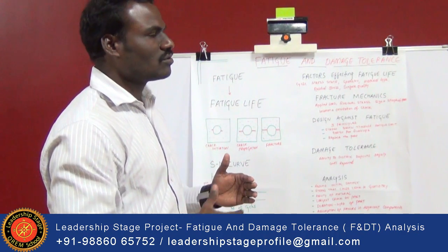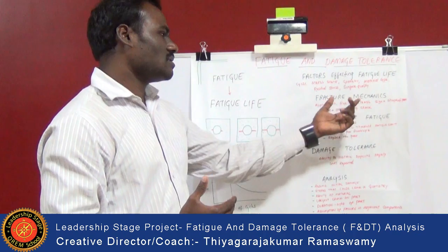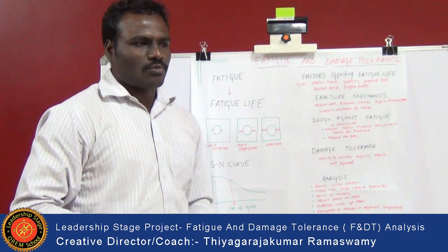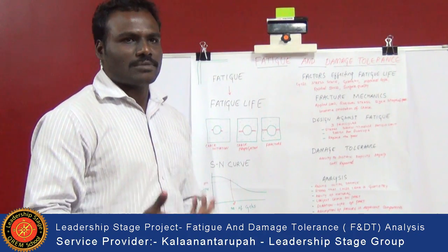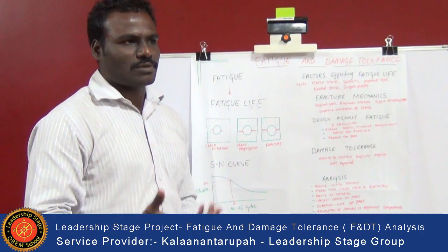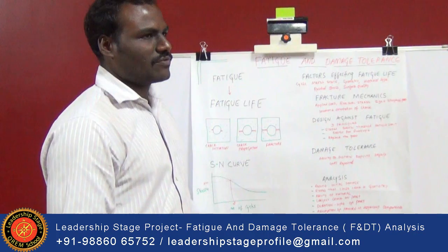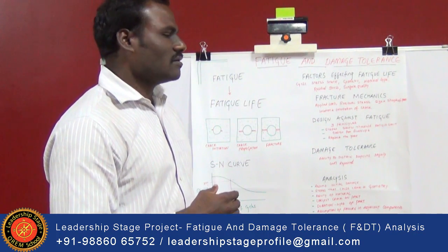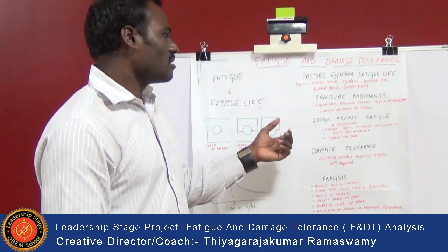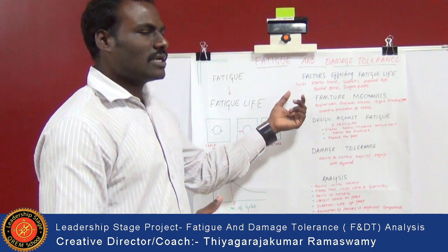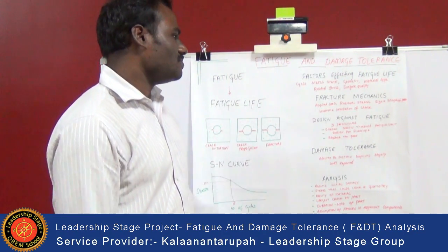With respect to the surface quality, there may be some voids or air gaps developed during manufacturing processes such as casting or molding, which lead to fatigue failure and decrease the fatigue strength of the material.